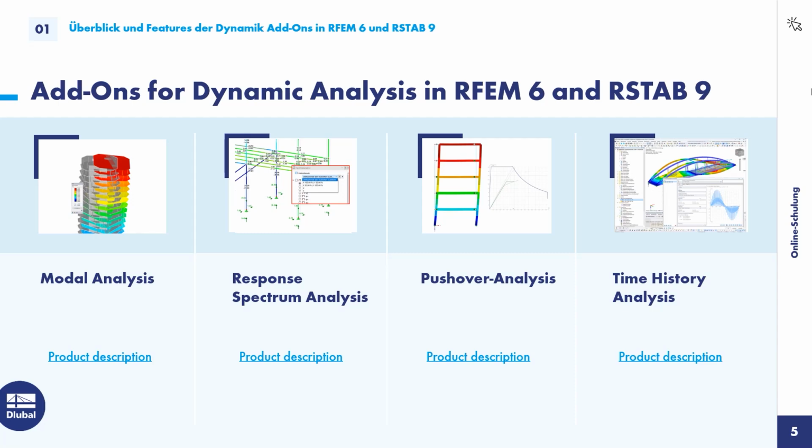So the pushover analysis also uses the modal analysis, since basically we consider a structure, and the structure is now being pushed from one side with an increased loading. And the distribution of that loading is given according to code. There are different shapes, for example, a rectangular shape, a triangular shape, and also a modal shape. So we need the modal distribution to create that loading.